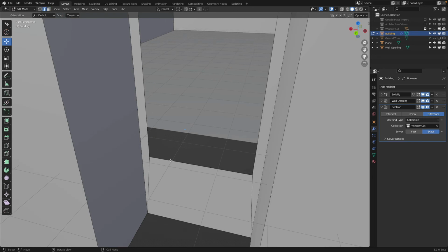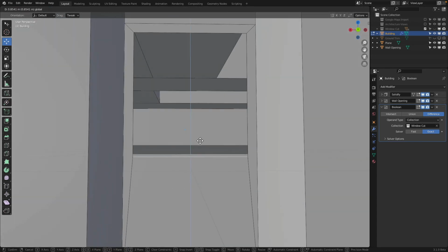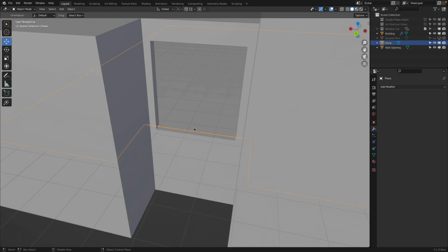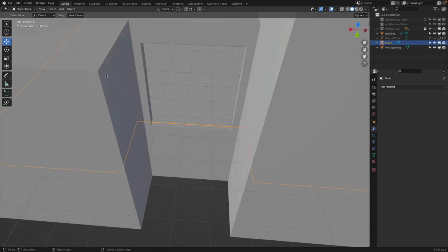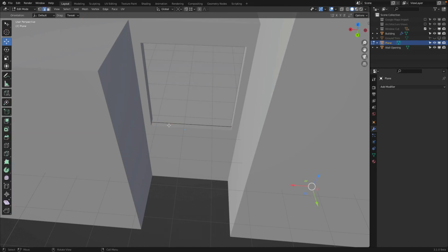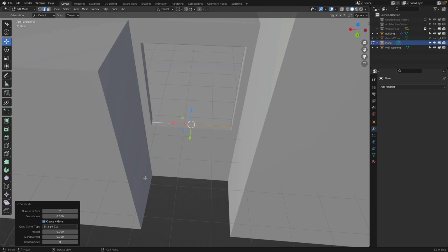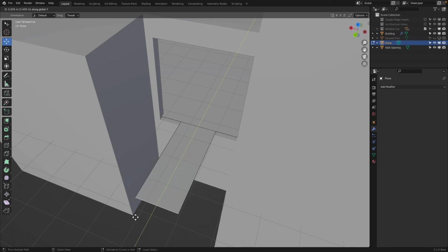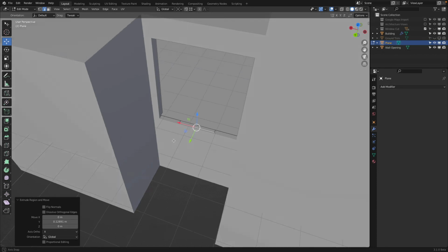This line here is not 100% correct. I can move this up so it's close. I could line this up perfectly. We just get it close. That's good. Because this floor, now we will grow bigger over it anyway. So floor geometry, edit mode, select this edge, right click, subdivide, so 2 cuts, and then edge select there, set segment, E and Y, go to maybe just to there.